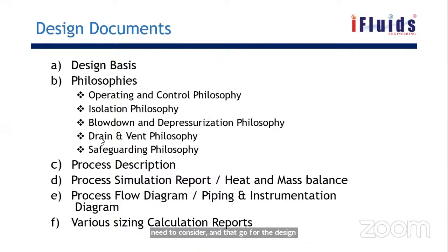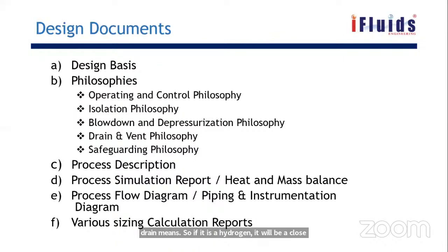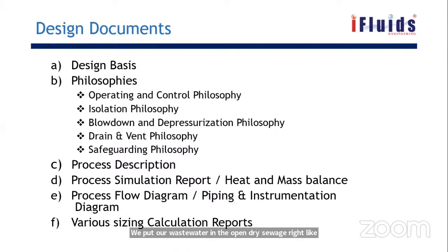And the drain and venting philosophy that we talked about. Drain means if it is a hydrocarbon, it will be a closed drain. No hydrocarbon will be put in an open drain. Like in our household, we put our wastewater in an open drain sewage, right? Similarly, in the industry, only rainwater will be captured in a separate drain, and process water that does not harm the ambient will be put in an open drain, and all the rest, the hydrocarbon and the process fluids, will be put in a closed drain.